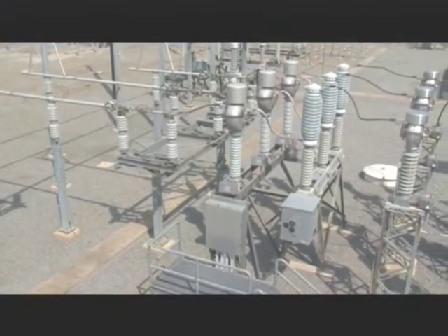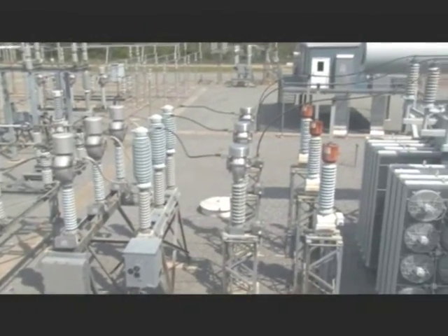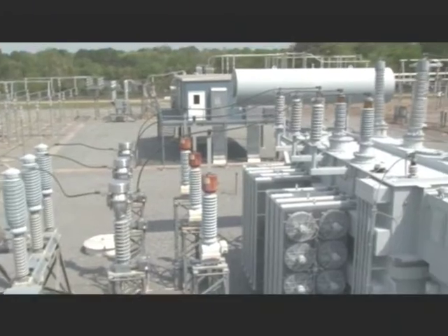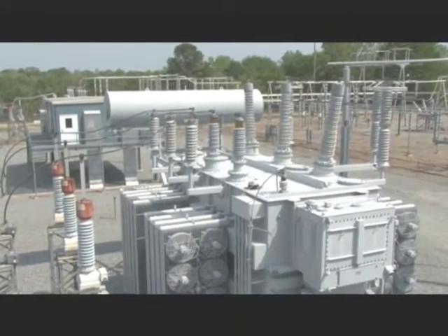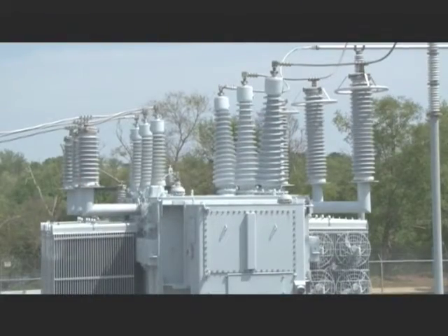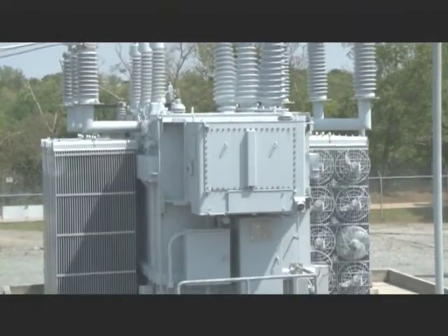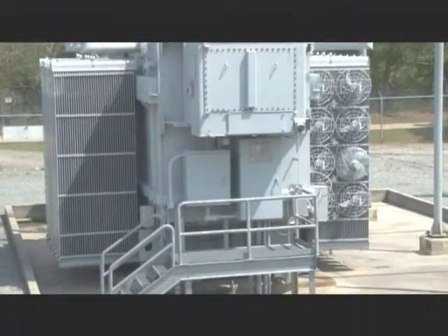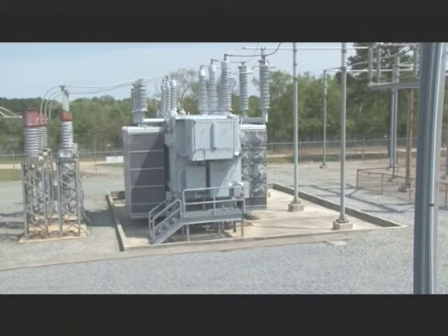Now that we know how to tell one end of a substation from another, let's take a look at the components that make it work. To make a substation, all you really need are station transformers, circuit breakers, and disconnects. First, we have to have the station transformer. In a sense, it's the heart of the substation. It's the component that reduces voltage from transmission levels to distribution levels.